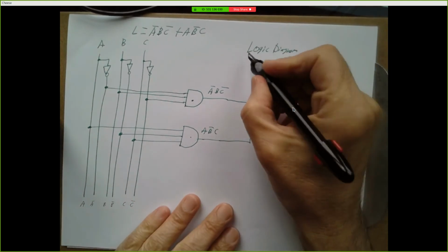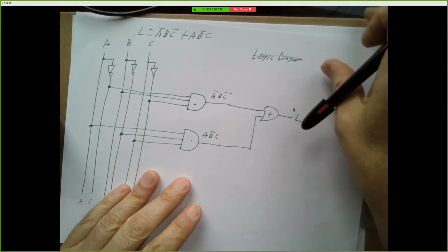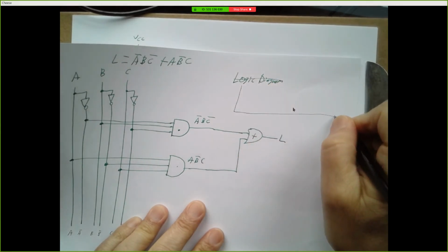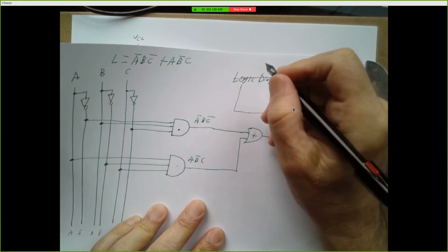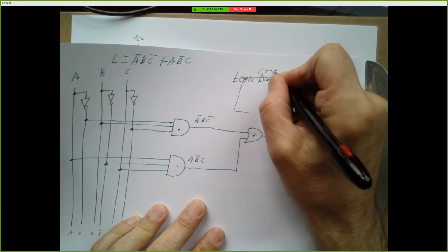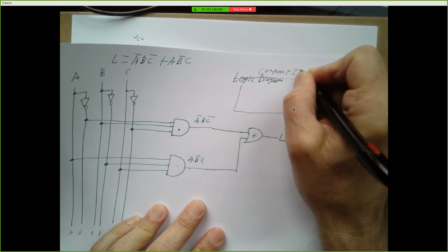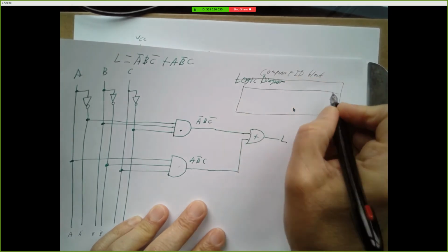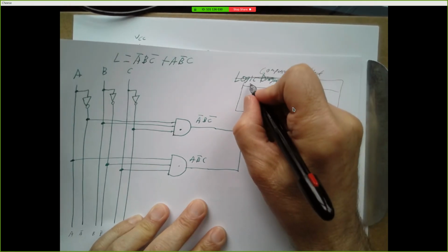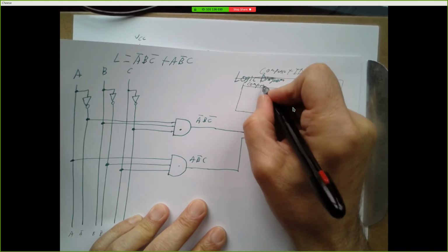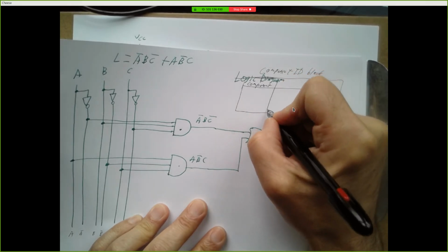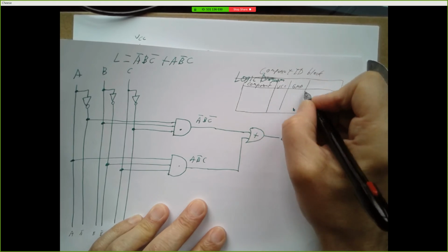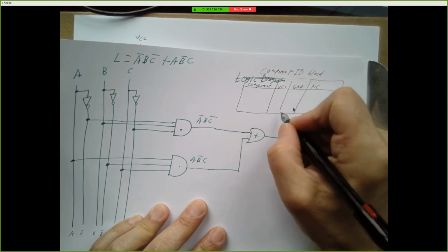We would see what's called a component ID block, up here in the upper right corner. Eventually this is what you'll be doing in some of the later labs. We have a block labeled component ID block. So it would say component, and we would say where do we connect VCC, where do we connect ground, and maybe where do we have no connections.